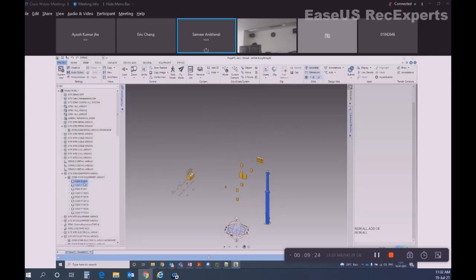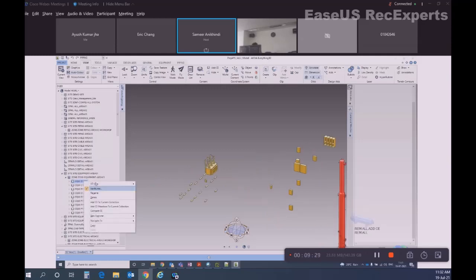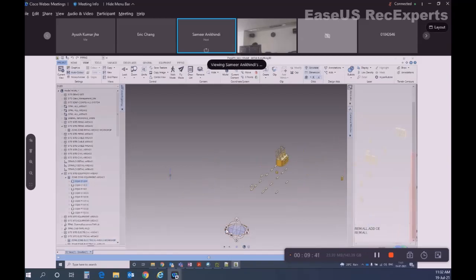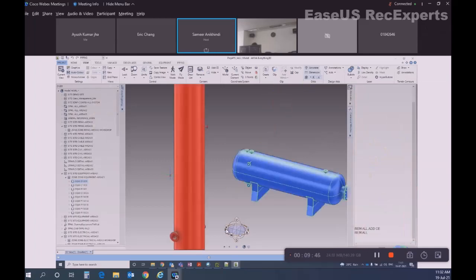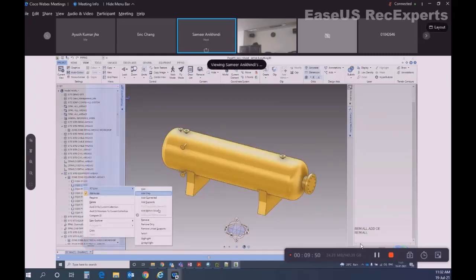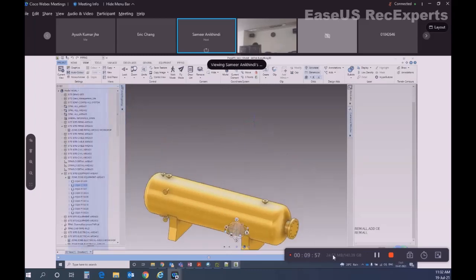Or what you can do is, you add this, but suppose it is not visible, 3D view select. So it is selected and press Z enter. Sorry, 3D view select, Z enter, O enter. It will zoom to that object because first you are selecting. Right click, 3D view select. Don't press to type the command. Don't press the left click. Just use middle click so that it does not lose the focus.